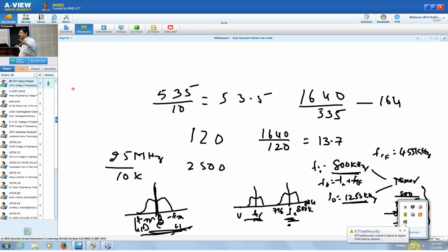All these things that we are going to discuss have amplitude variation. So you have a limiter to eliminate the amplitude variation in FM reception. Whereas in the case of AM, you can't provide a limiter. If you provide a limiter, the information in the amplitude will be lost.